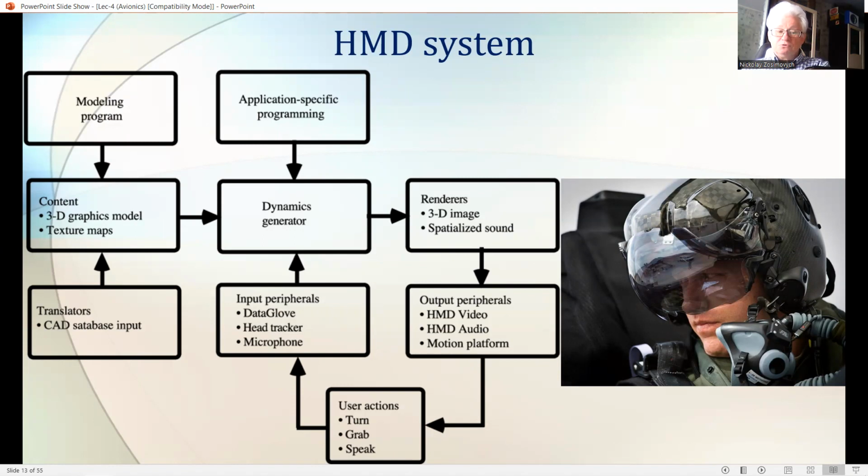It appears feasible to devise self-monitoring techniques to check the integrity of the head tracker system. Alternatively, a dual tracker system would be installed as a monitor or used in conjunction with a self-monitoring system. An alternative get-you-home source of attitude could be obtained from a triad of miniature solid-state gyros and accelerometers mounted directly on the helmet, and computing the helmet attitude from there.